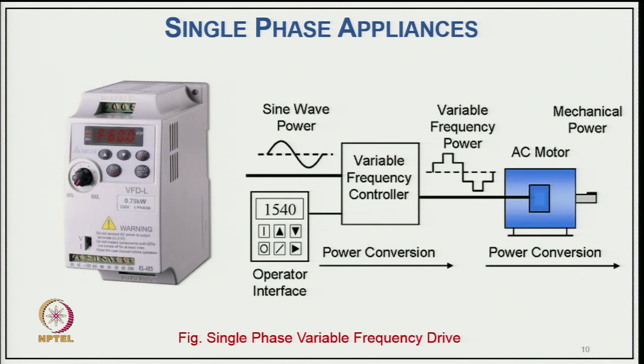Then you have inverters: we have single phase variable frequency inverters used for many applications, maybe domestic applications, or variable frequency motor control. You might have a single phase supply, but the motor may be 3 phase, because you can convert the single phase supply into DC, and from DC convert to a 3 phase supply of variable frequency. It gives a real boost to AC motors, since you can run 3 phase AC motors, which are much more efficient as well as cost effective.